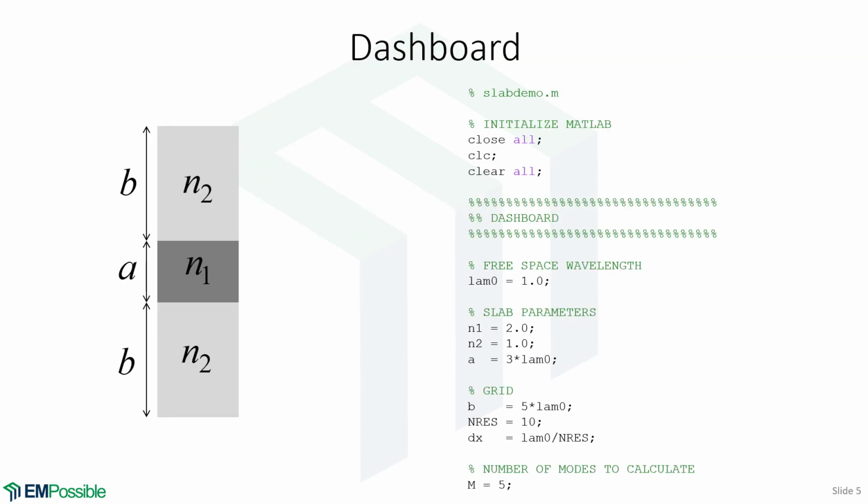So you're going to see every line of code in MATLAB to simulate this slab waveguide using the techniques that we've been discussing. So first is the dashboard. I like to start my programs with the name of my script file, slab demo. And of course, I like to initialize MATLAB. So we'll close all open figure windows, clear any text from the command window, and then the most important, clear all variables from memory.